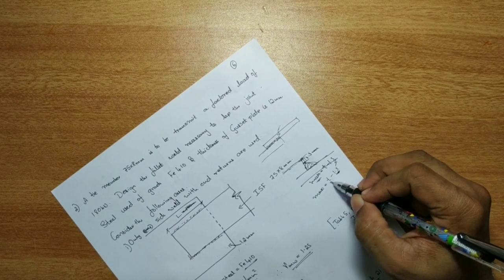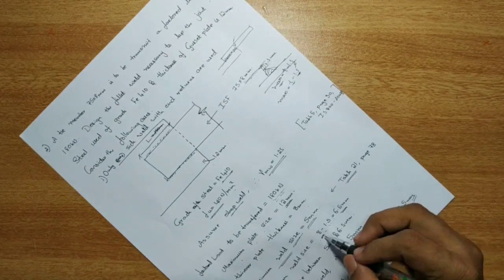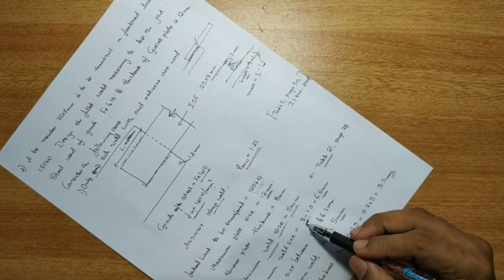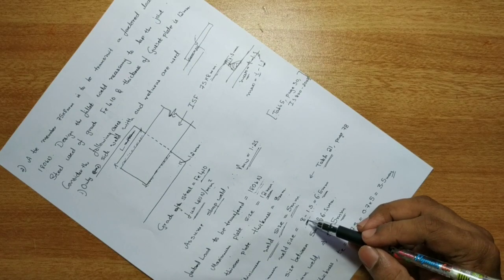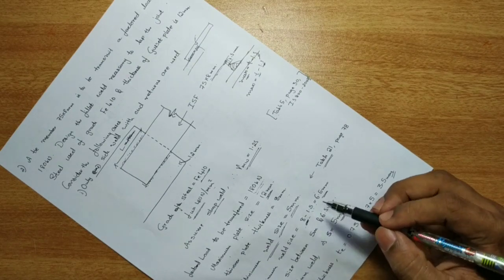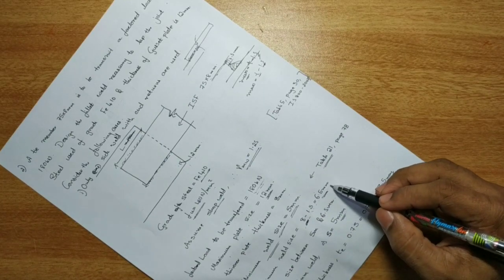This is a gap and this is the thinner plate. So here the maximum weld size becomes, the thinner plate is 8 mm. This is 75 into 8 mm, 8 mm is the thinner plate, and minus 1.5. You need to consider minus 1.5 here, so it becomes 8 minus 1.5 is 6.5 mm.